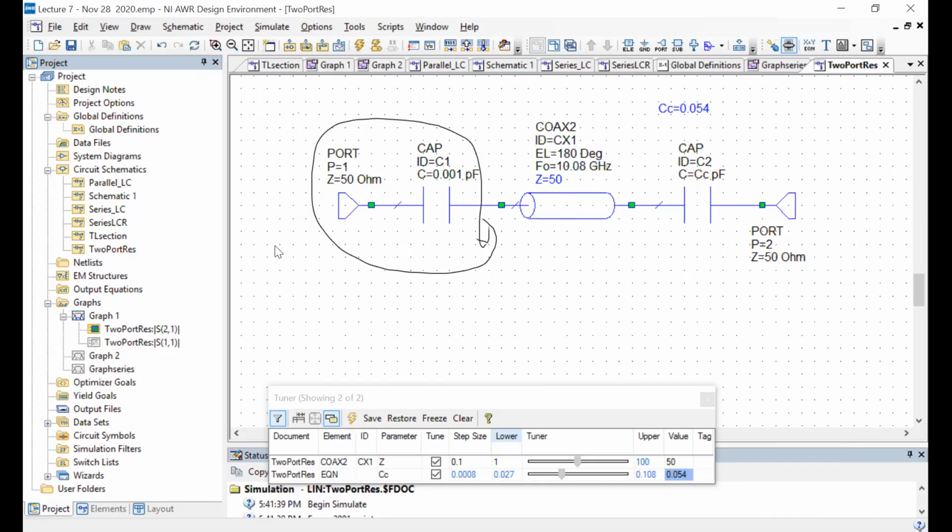This is like an extremely weakly transmitting mirror. So from the perspective of the resonator, the amount of power leaking this way is not so important, which means the loss or the Q factor of this is entirely set by this part of the circuit.